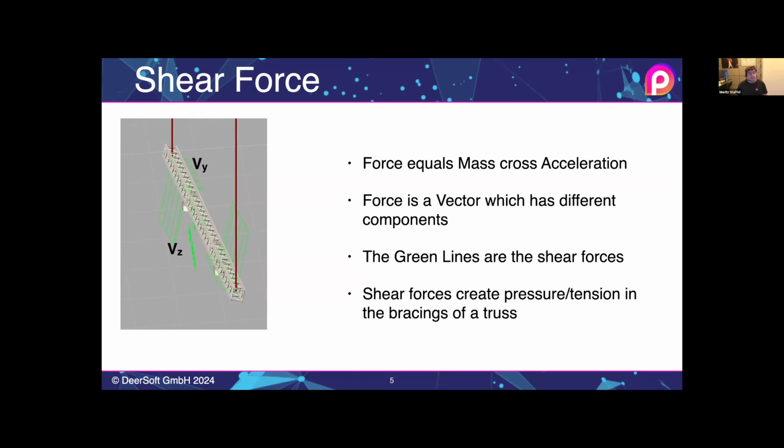So in this case, the vectoral force from the lighting device, which you're seeing in there, is pointing directly down. But because the truss is a little bit tilted, these forces need to be recalculated for the raked truss. So part of its weight goes into Vz, in this case the majority of the weight because the line is longer, and Vy takes the other part of it. If you would do a vectoral addition for Vy and Vz, they would point directly down.